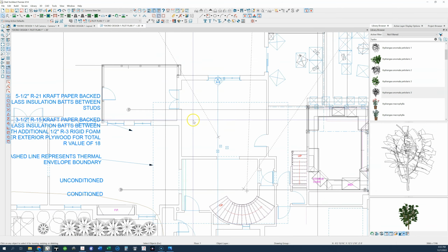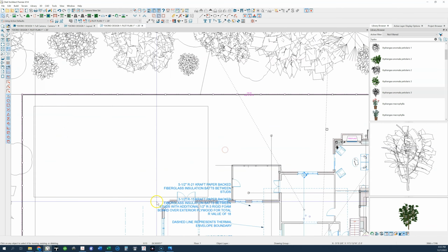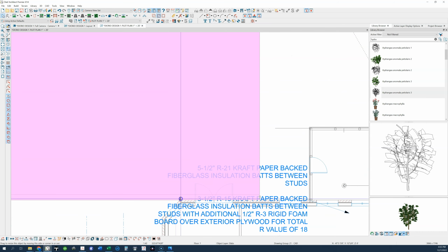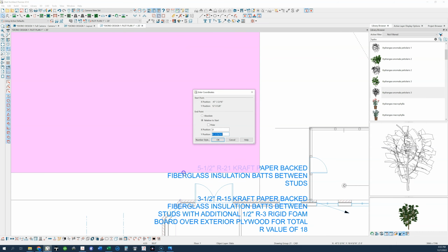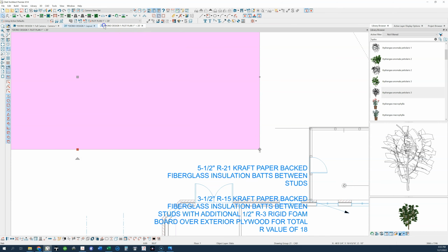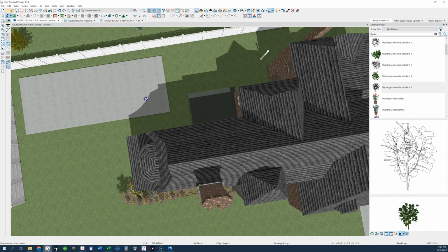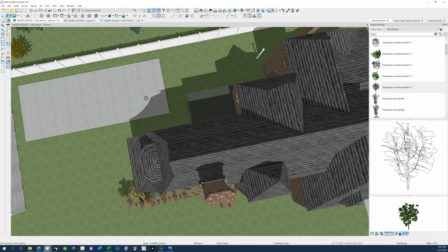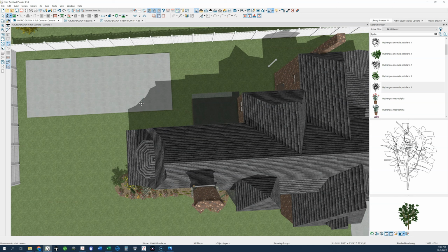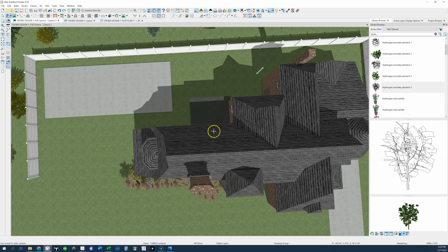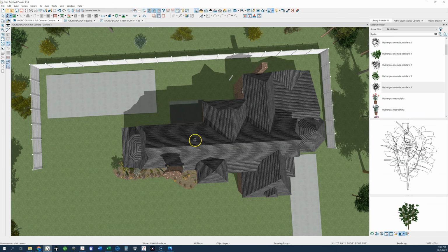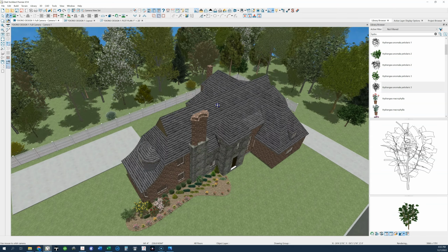If I work on 8 feet, let me see where. Okay, so this will be the 8 feet. So that's where your rear roofed over patio can legally be. There are some other issues as far as lot coverage, maximum building coverage, maximum floor area ratio, which is all floors combined. And then there's also another one for maximum impervious area on the lot. I'll figure those out later as we go.